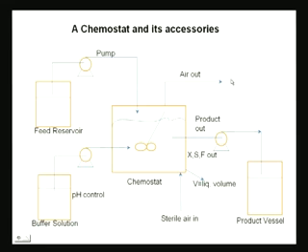You have air being taken out and replenished. Those kinds of things we have talked about. You need a certain amount of oxygen into the system and so on. So, the air is taken out here and replenished from here. The sterile air comes in here just for the oxygen that you need to supply, and the nutrients, that is the carbon and nitrogen in liquid form, are a part of the feed reservoir itself.